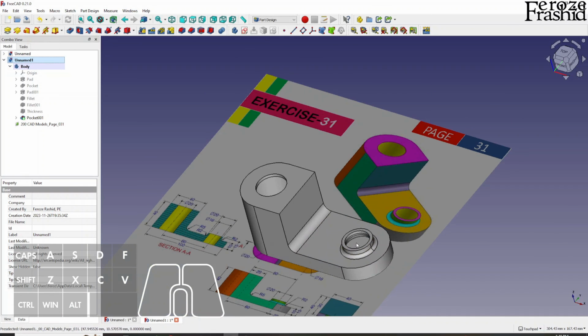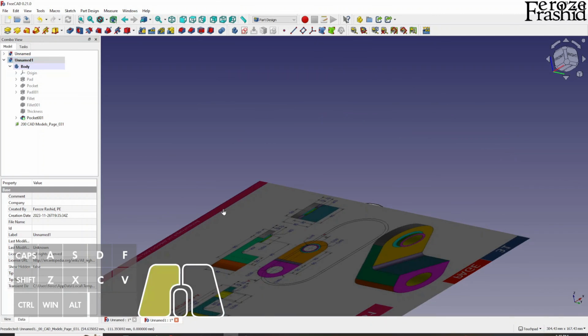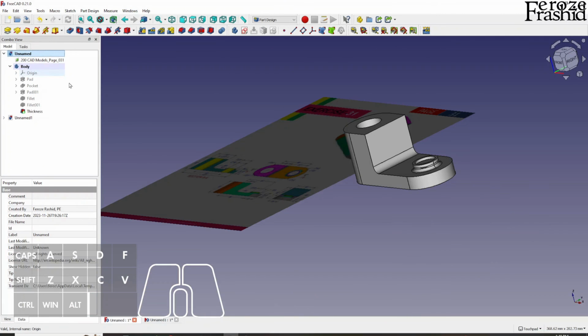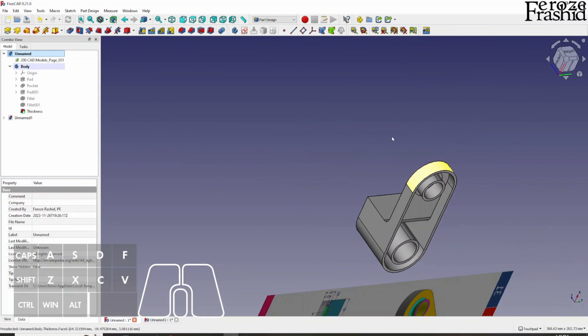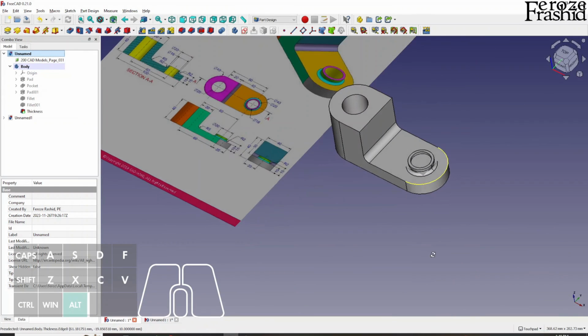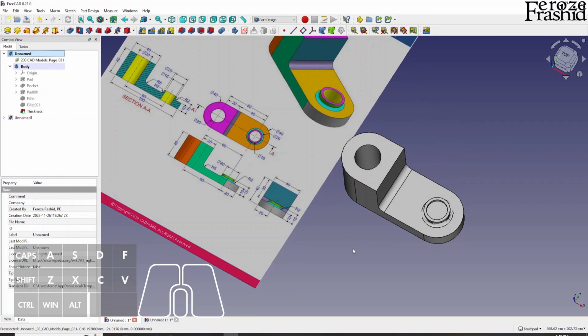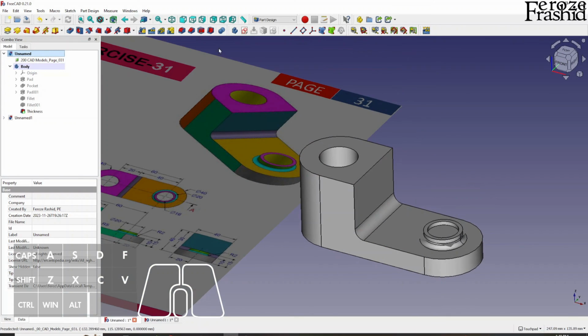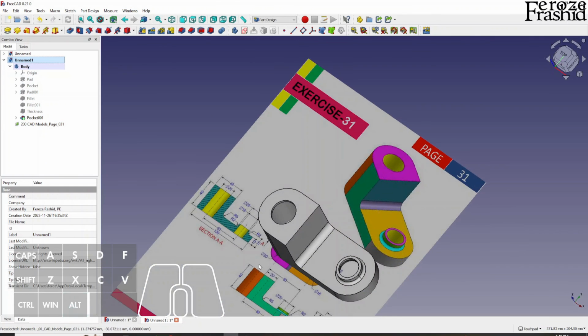Is it this one that is completely hollow inside, or this one where I wanted to have 2 columns to support the hollow side? I hope you enjoyed this video with the little tricks on the thickness tool, just how important the work tree is, and by modifying the work tree, we can achieve different things in the same workbench.